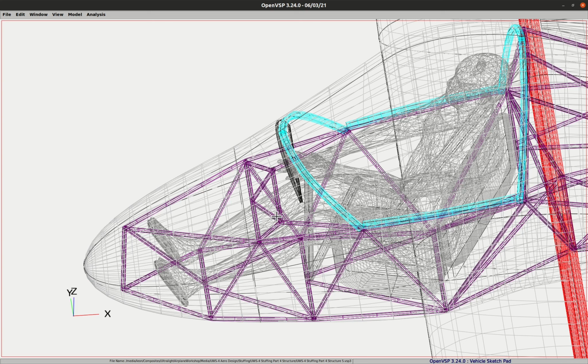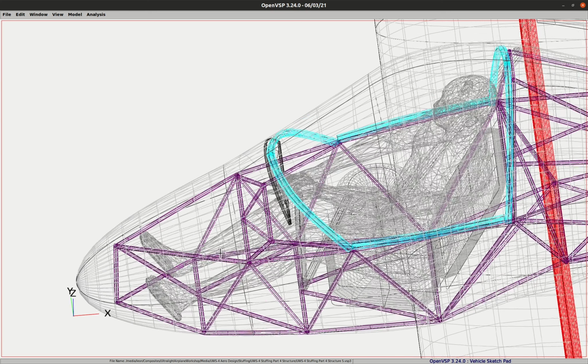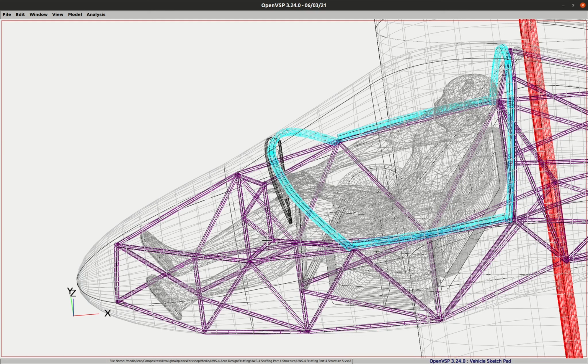It's not perfect. It doesn't have to be very heavy. Since this is in tension, most of this will be in tension also. That's assuming symmetric load. Now if we hit sideways and up, then it's going to be an asymmetric load. So we're going to have to do some analysis to try to figure out what size these tubes should be.